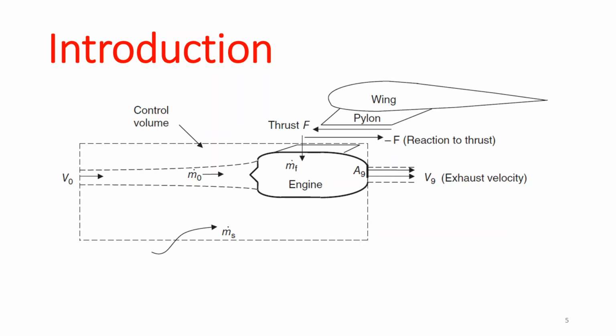So the inlet part is very far away from your jet. So essentially the effects of the jet are not going to be seen at the inlet. And the exit part, the outlet part, includes all of the exit of the jet and some of the ambient air and pressure. We also have the other part of the control volume far away from the jet engine walls.